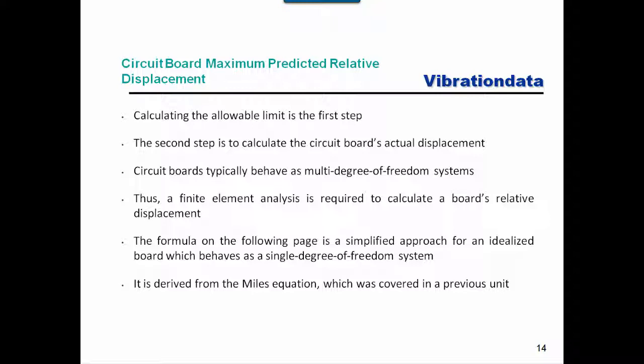So we can, for the most part, get away with some simplifying assumptions. But having said that, yes, there are exceptions. So if there's any doubt about what I just said, please do finite element modeling. If you can do some type of modal test on your circuit board, that's great too. That data is useful. But we're just going to go ahead and assume a simple single degree of freedom system.